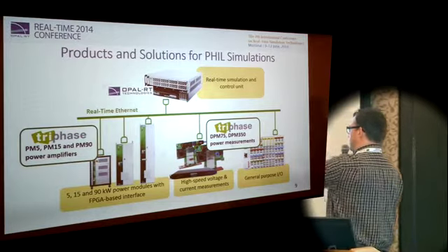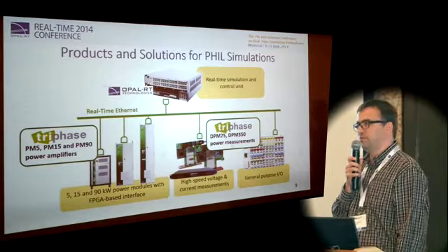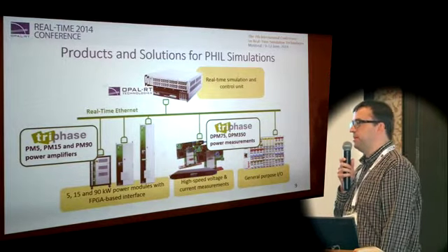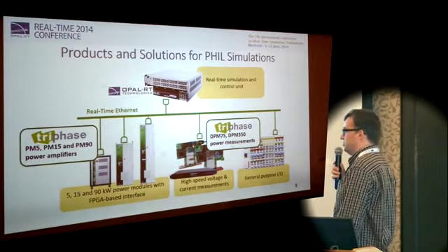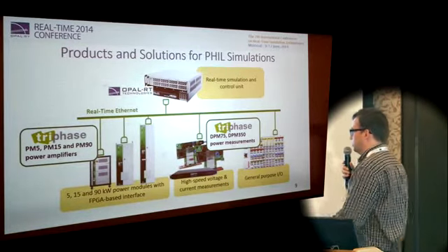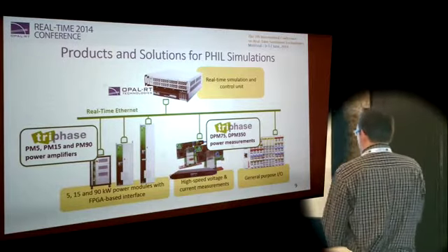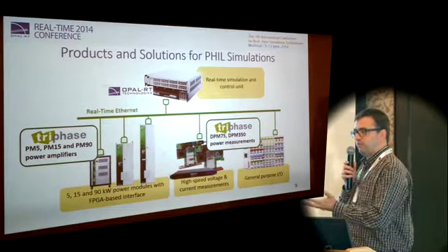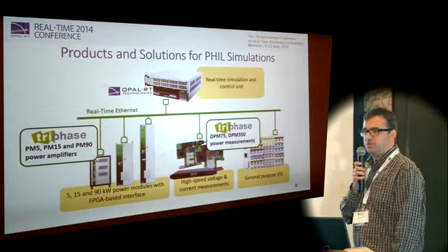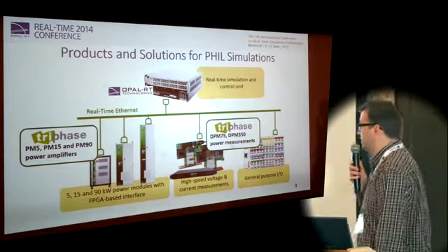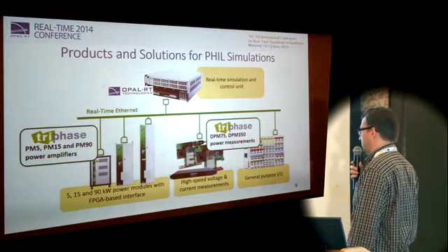Actually, you're going to see an Ethernet wire from the computer to the first device, then a wire from the first device to the second device. So it's a minimal wiring overhead solution. The advantage is also it's very easy to connect a whole bunch of measurements, amplifiers, and also additional I/O to your system and have all the data fed back into your OPAL-RT simulation unit. So you can actually do some interesting data crunching inside the simulation unit.